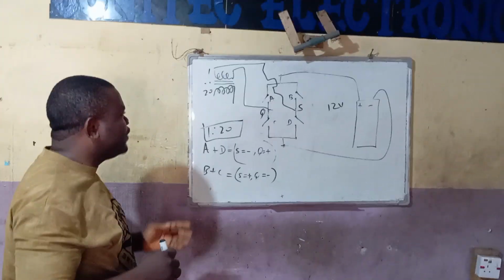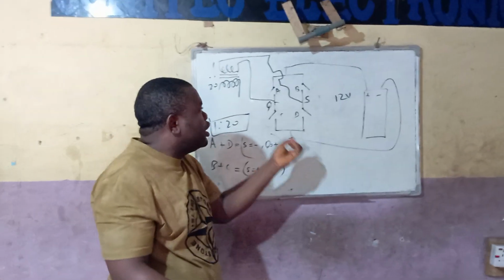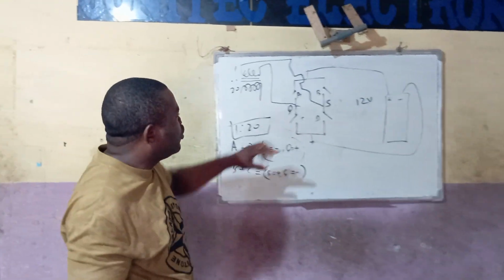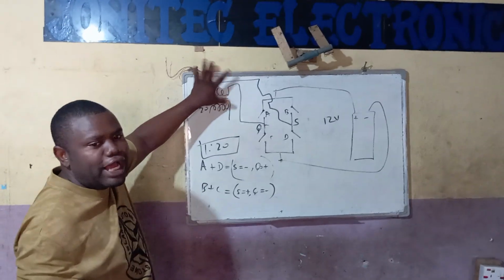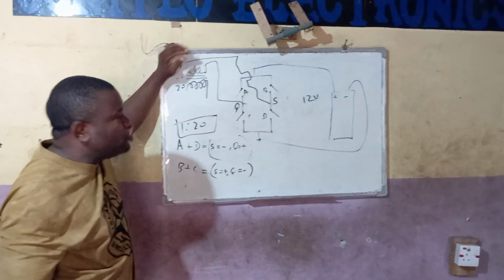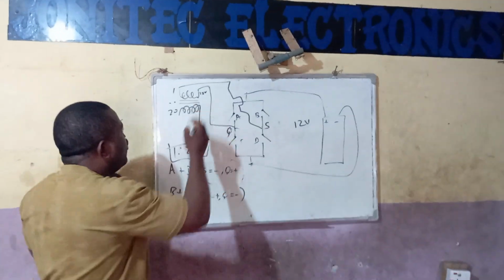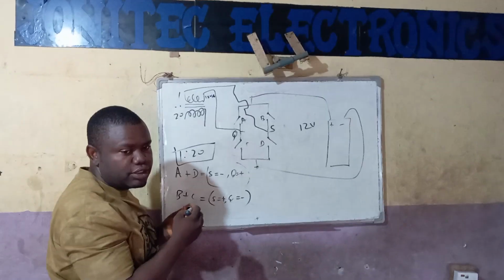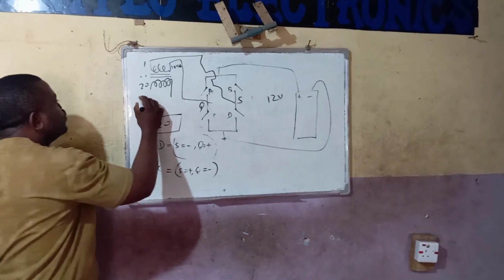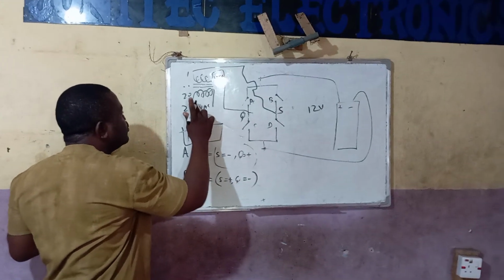So that at the first instant, when the H-bridge is changing its polarity so fast, the current is being sent through these two wires to the what? The transformer. The transformer does the job by stepping it up. So if 12 volts AC comes in here, it sends out 240 volts AC. Are we together?